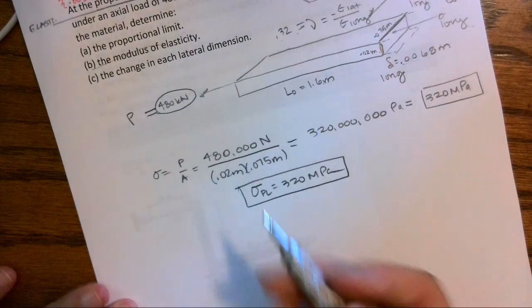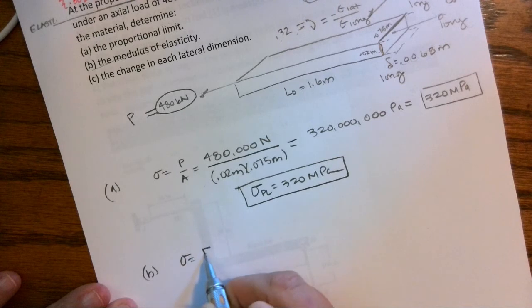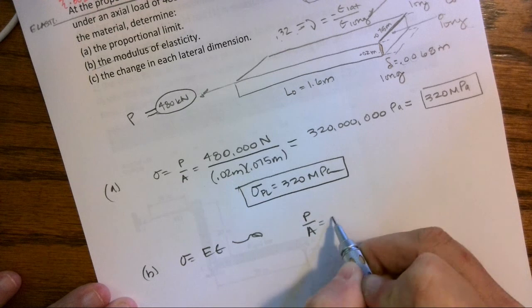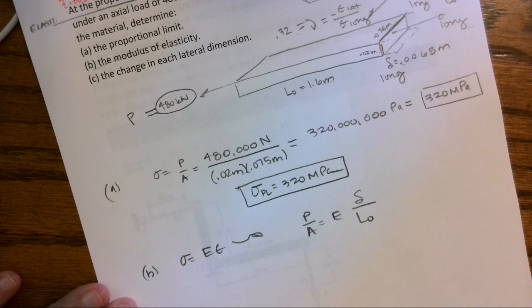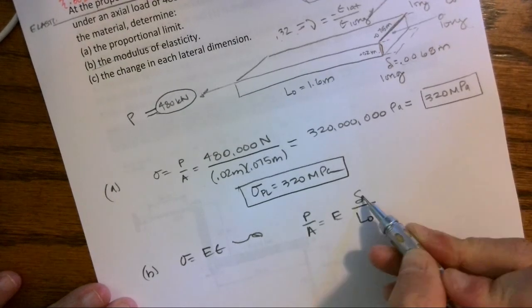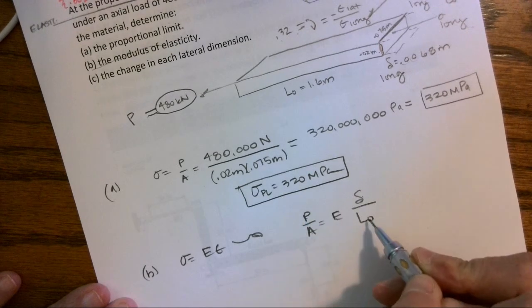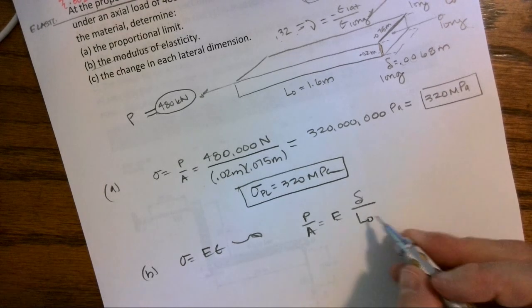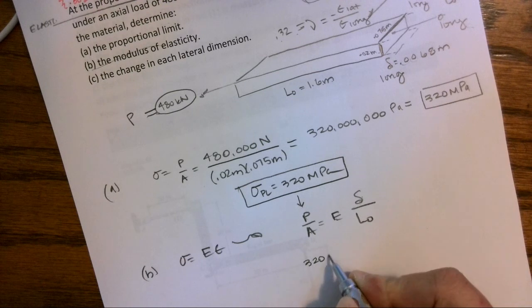So this was A. Well, I know that stress is E times strain, which tells me that P over A equals E times delta over length initial. And I can rewrite this however I wanted. If I wanted to find delta, delta would be PL over AE. E is going to be PL over A delta. You can just rewrite this equation. I've already figured out my stress, so I have 320 megapascals,